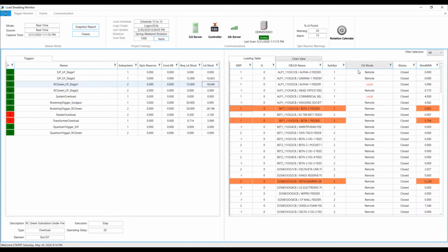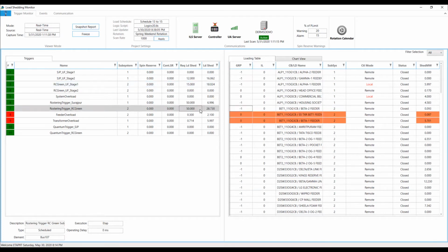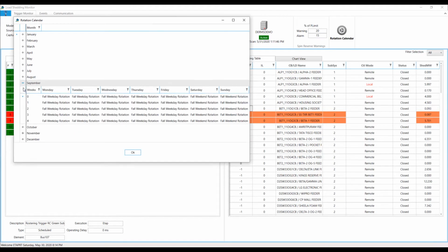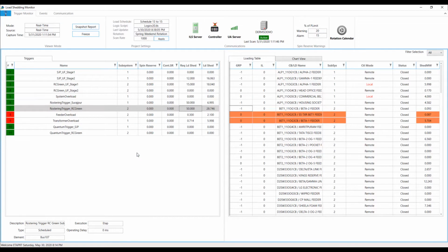Non-essential loads with the lower priority will be selected to be shed first based on the system conditions and operating levels. Essential loads will be selected only if the non-essential loads cannot satisfy the requirements. There may be some loads such as hospitals, clinics, emergency services that need uninterrupted reliable power supply, and the load shedding system will not shut them off and ensure that the system reliability is maintained to provide services to these key loads.